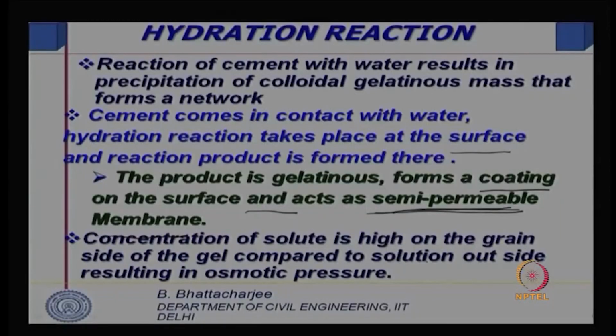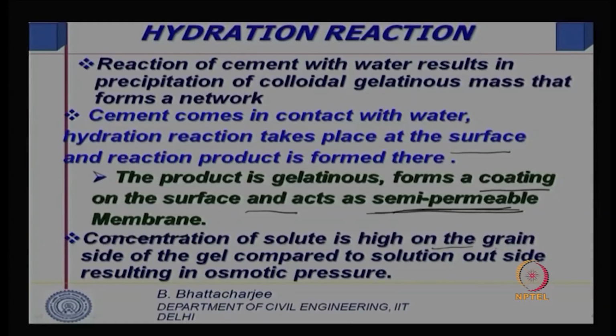That will result in rupture, breakage of the semi permeable membrane, and water will penetrate into the unhydrated portion of the cement, and thereby the hydration reaction would progress. So, the concentration of solute is high on the grain side of the gel compared to the solution outside, resulting in osmotic pressure,